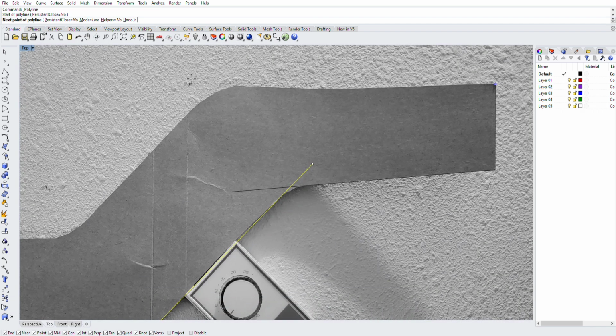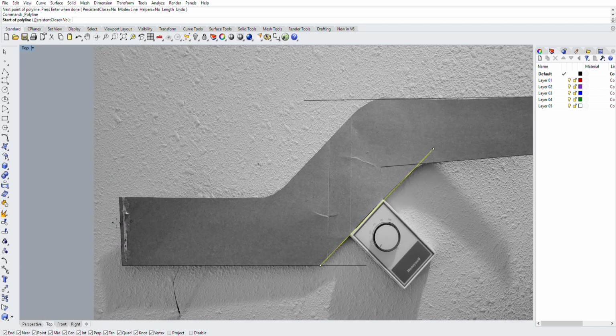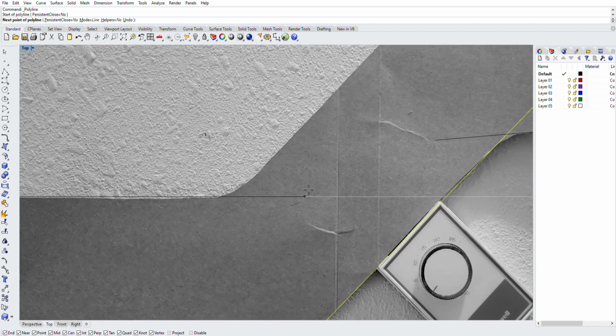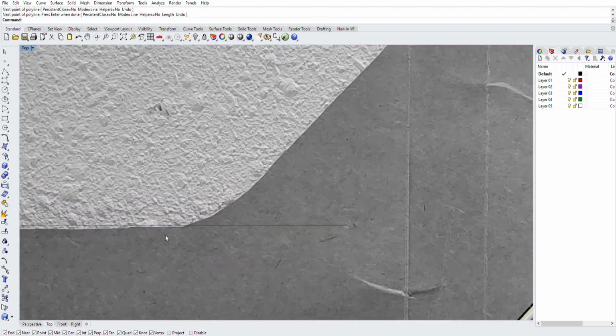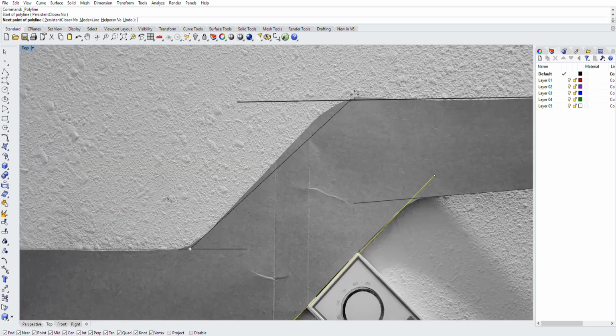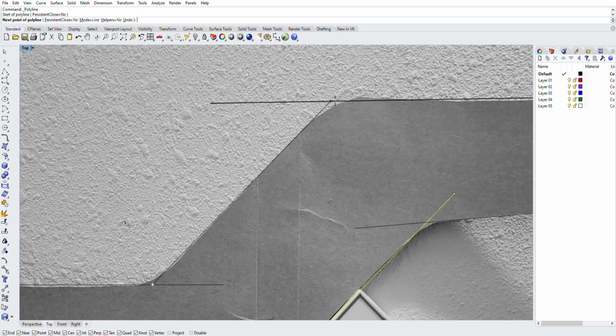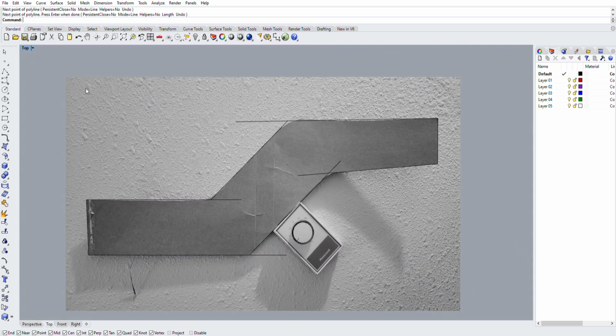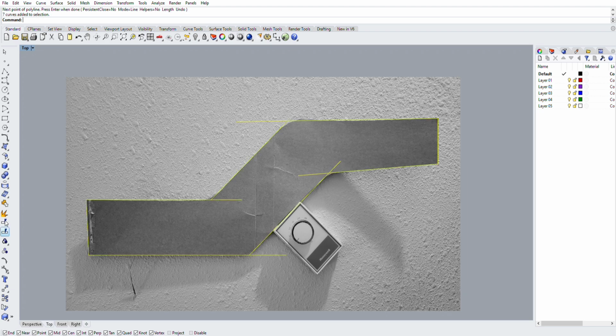I usually take them on concrete floors, with as little background as possible, stark contrast because we want sharp lines like we have here, but weigh it down with something. Put a paint can on it, put some sockets on it. A lot of the times I'll even take a picture with a tape measure in the picture. So if someone's emailing me a template, I can literally lay a tape measure in it. I can scale it to the tape measure because that's a known value. And I don't need any measurements. I've got it all in front of me.